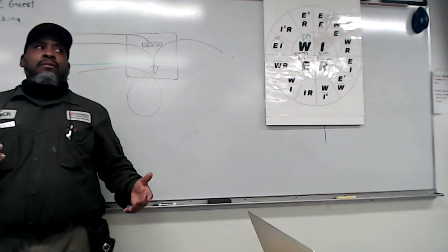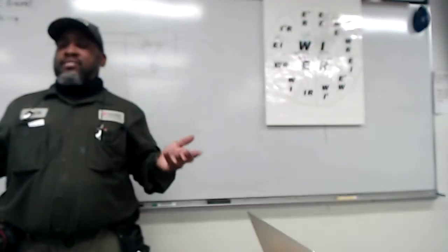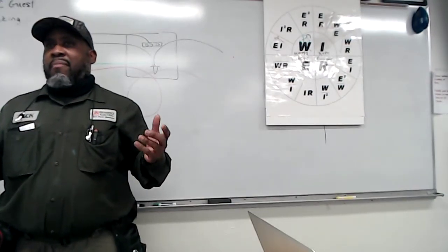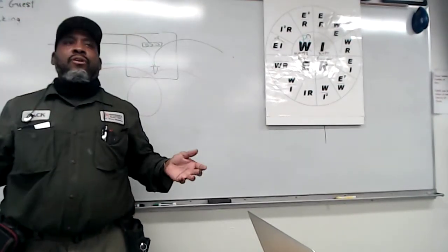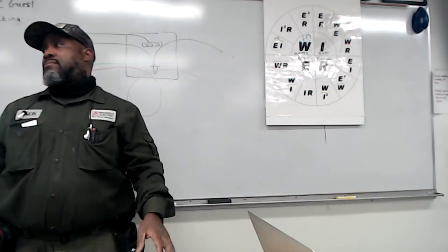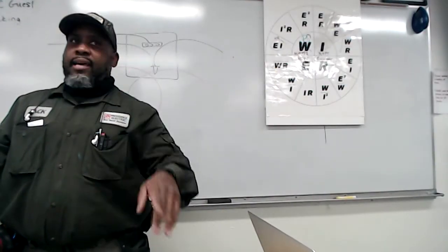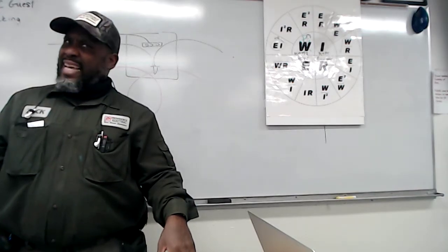So I don't know if you guys ever put a light fixture up in the ceiling, but every light fixture has to have some kind of support. Okay? You don't just mount a light to the box. It has a bracket. The light has a hanging bracket. Does that make sense? If it has a hanging bracket, it gets counted one time. Why? It takes up space, exactly.